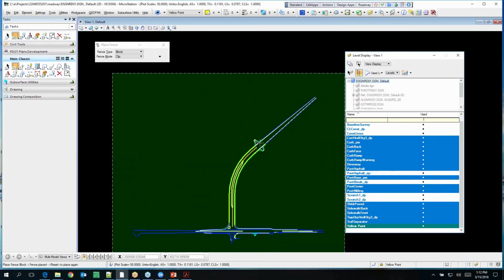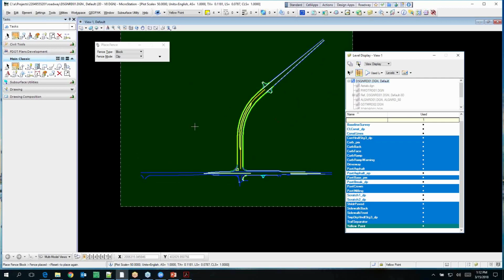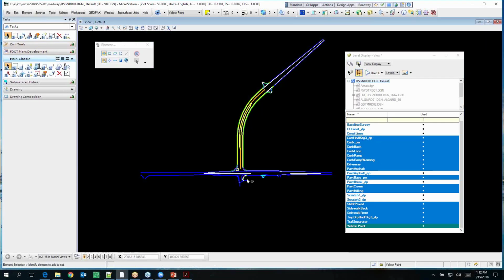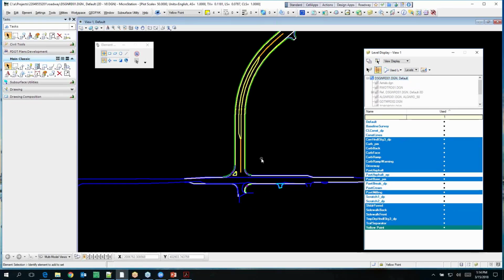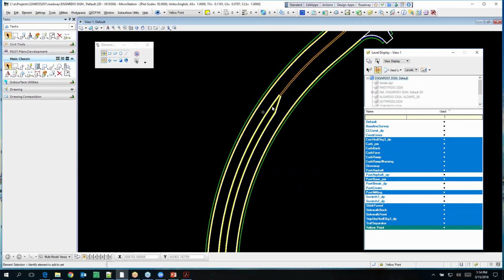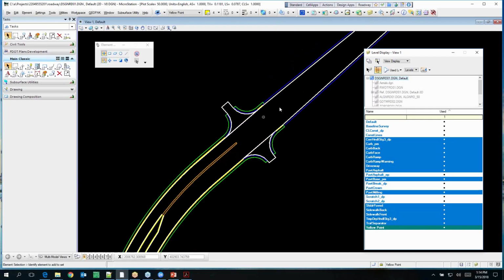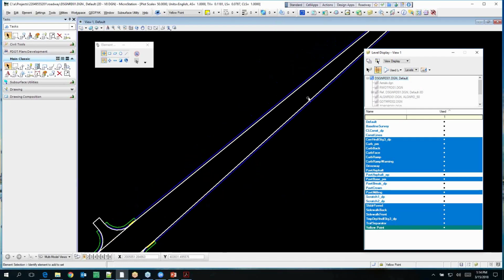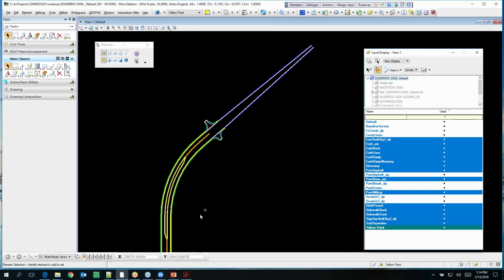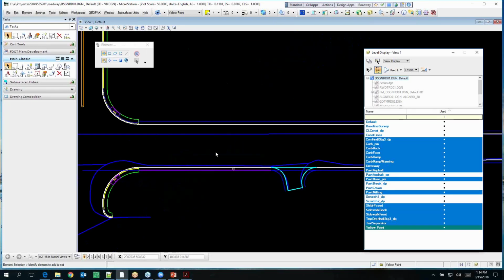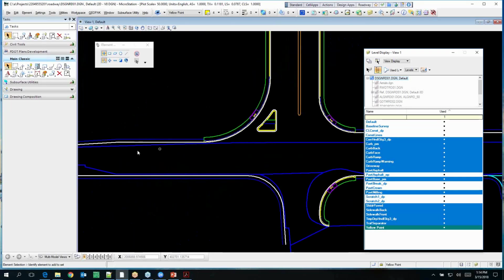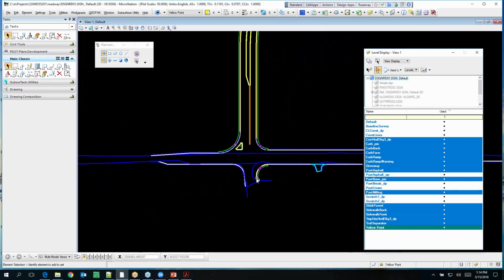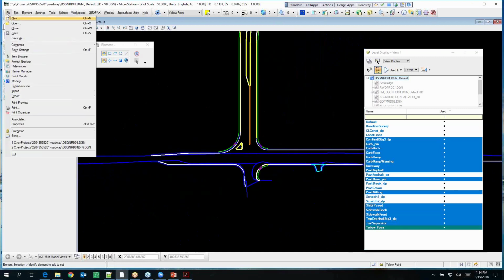I didn't look well enough at that point, so I should have. Let me get rid of that fence. Start over, so get it nice and clean. Let's see. This is all proposed construction lines. Nothing else, just 2D. These are our milling lines. We do want those. Edge pavement lines, that's where we're widening to. So yeah, this looks good. So that should be ready to export now.